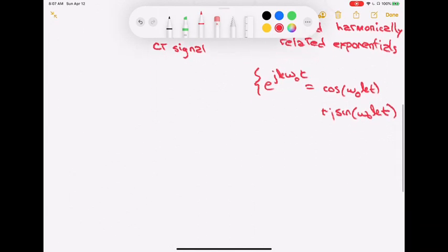Okay, why is that so important? Well, part of this should be pretty obvious at this point in the class. We know that exponentials are incredibly easy as far as how they go through linear time invariant systems. If you put an everlasting exponential in, you get the same everlasting exponential out modified in gain and phase, or modified by a complex constant depending on that system function. So some motivation for the Fourier series, and we'll start abbreviating the Fourier series as an FS.